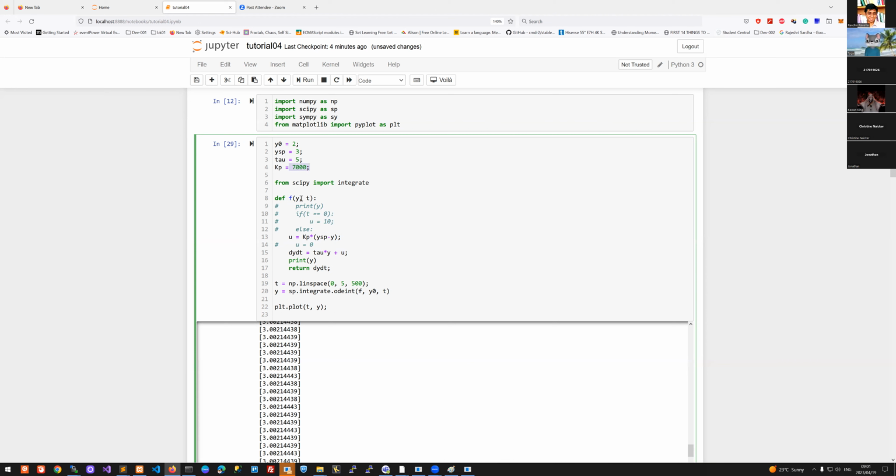We can just simulate the ODEs and play around with the values. So the KP value or the tau I value. And you can change your process type here, and you can use the integral as well. You'll need to write in some numerical integration also, which you can do. And then you can see whether it achieves your control objective.